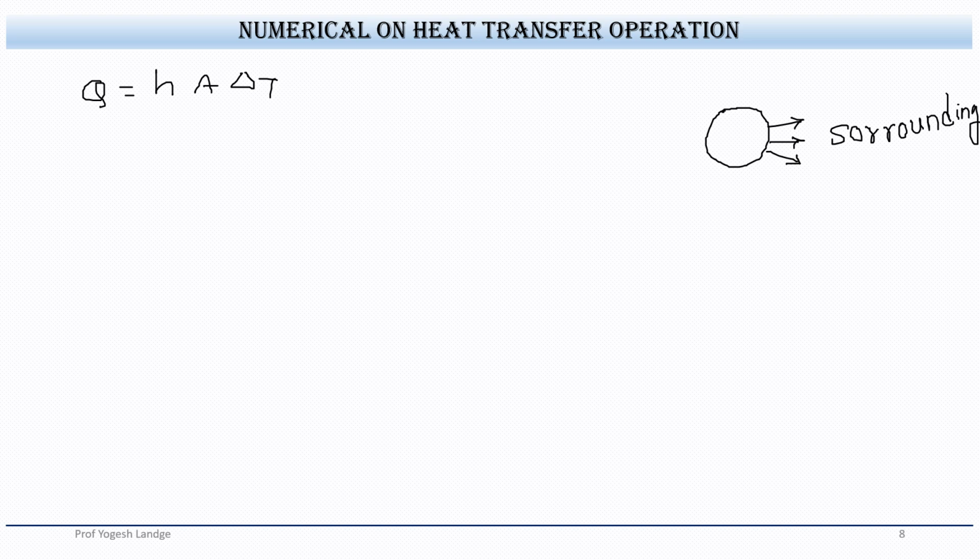On the basis of the data, we know the value of R3, we know the surface temperature 50, we know the surrounding temperature 25, that is T3 and T2. Also the H value, the surrounding heat transfer coefficient, is given, so we just put in those values.